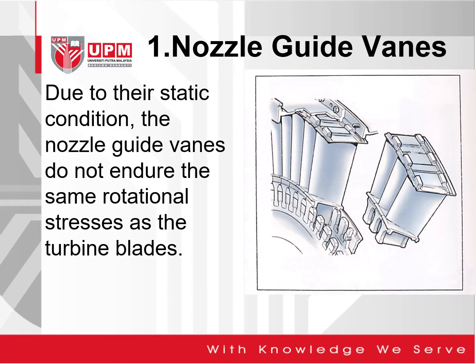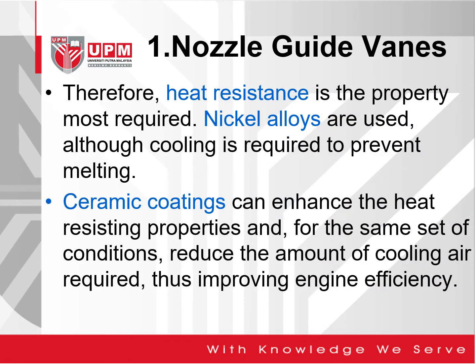Due to their static condition, the nozzle guide vanes as shown here do not endure the same rotational stresses as the turbine blades. Therefore, heat resistance is the property most required. Okay, you want heat resistance. And nickel alloys are normally used, although cooling is still required to prevent melting.